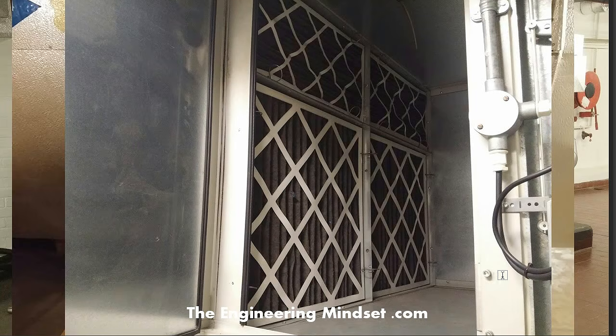And just to give you an example here of how that would look inside the AHU in real life. So we've got 4 panel filters of different sizes, obviously. Slightly different design here by a different manufacturer, and also the material that is used, the thickness of this filter material is what's going to capture the most dirt and germs, etc., that's going through there. And the AHU designer, you can even bring filter specialists in, and they will advise you what filter material you should use. There's some standards which you can look up and read as well.